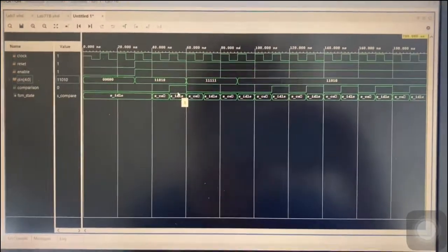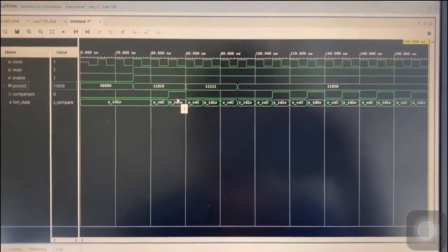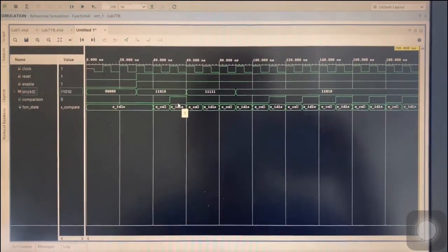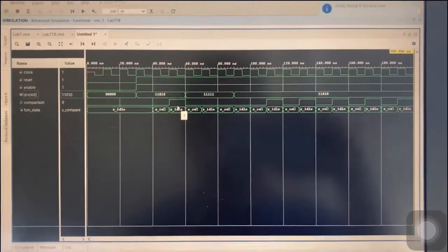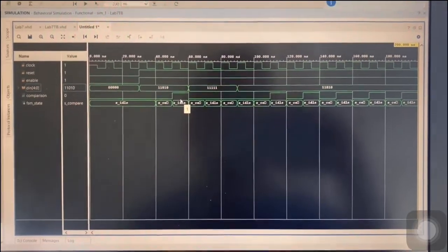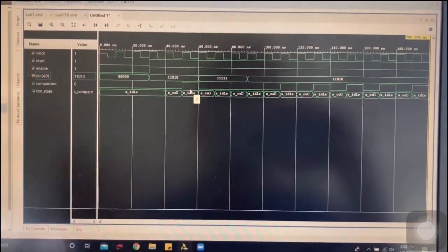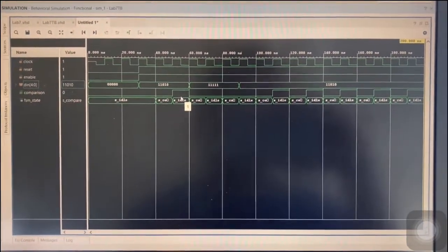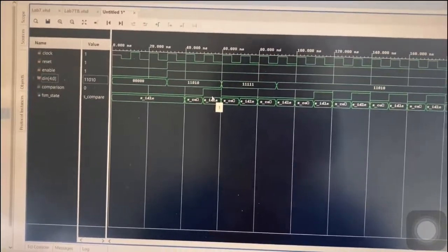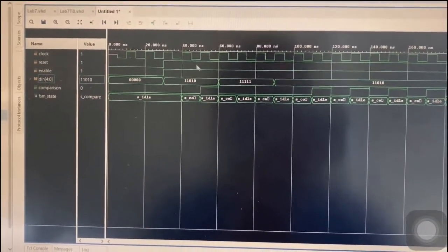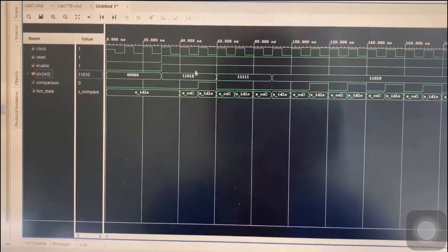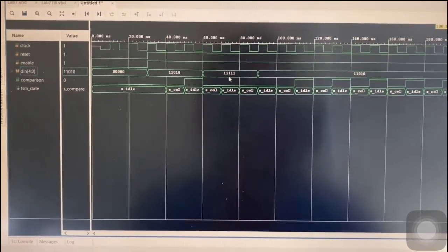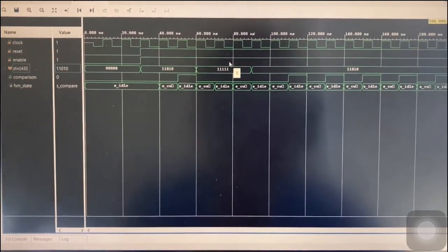Because I haven't built an FSM that uses current state, next state functionality, it's just whatever my current state is, and every output is really associated with the state before it. That's how this is working. So that's why my output goes high during idle instead of compare, and that's why my compare is delayed by 1 clock cycle. I hope this timing is starting to make sense now. But now also notice when my input is not that matching sequence, it just stays 0.